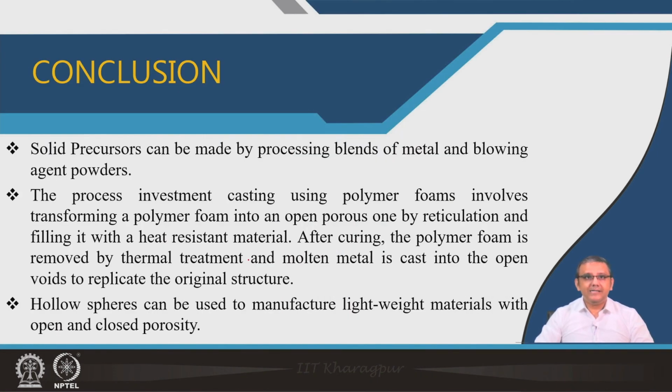To conclude today's lecture, we learned about various processes. We learned that solid precursors of aluminum powder or some metal powder and some foaming agent like titanium dihydride, zirconium dihydride or calcium carbonate can be blended together, and then after blowing we can obtain very nice porous structures.